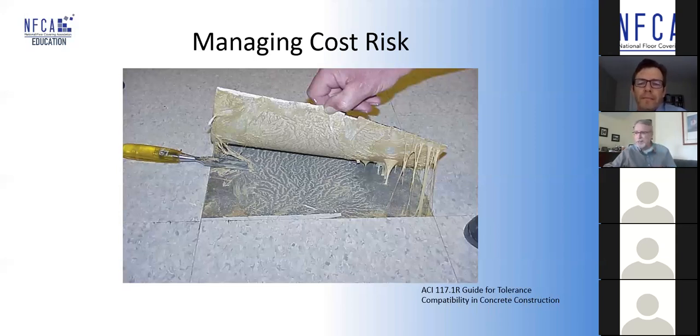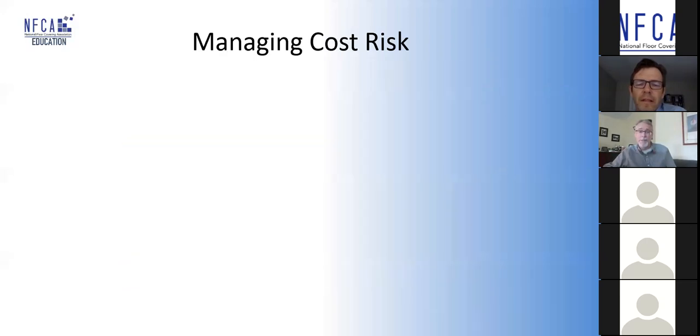If you have a 100 mm slab, the slab will dry out at a rate of about 1 mm per day. So that 4-inch thick slab will take about 100 days to dry, provided you have good curing conditions. If you have no temporary heat and you put down the concrete in September and it stays cold and wet for 6 months during winter, it's still wet in the spring. And it is the alkalinity that's present in the moisture that is eating up the adhesive.